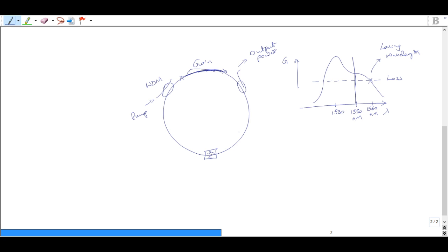Then what we are doing in this case is we are introducing a circulator inside the cavity. A circulator is an element which allows light from port 1 to go to port 2, and any light reflected from port 2 goes to port 3, right? So we introduce this element called a fiber Bragg grating, which I have explained during the regular lecture.